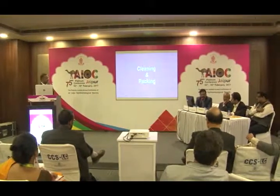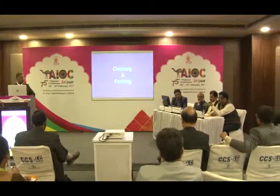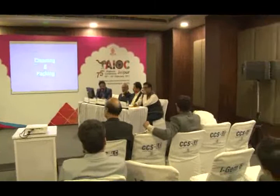Now air changes depend on the type of your operation theatre. If it is ophthalmic theatre, 15 to 20 is the recommended. But if your volume of operation is very high, you can increase the air changes. It cannot be fixed. It has to be dynamic. Yes, there is no controversy at all. Air pressure ventilation is mandatory.